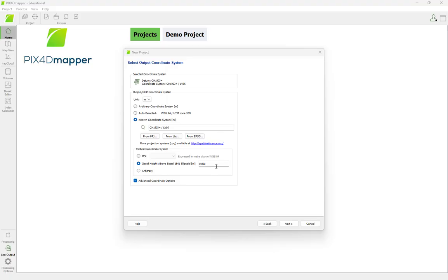When working with the WGS84 ellipsoid, the geoid height is 0. If you need your deliverables defined with a local or global geoid model not included in the list, it is best to use Pix4Dmatic, which is compatible with a more extensive selection of global and local geoid models.